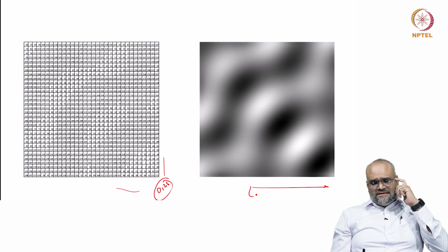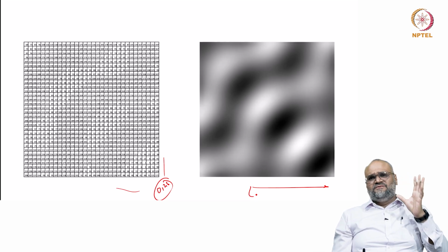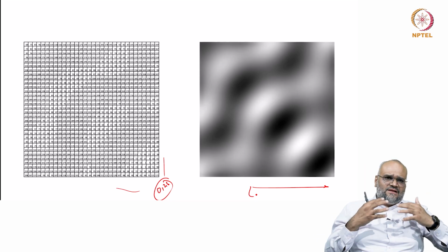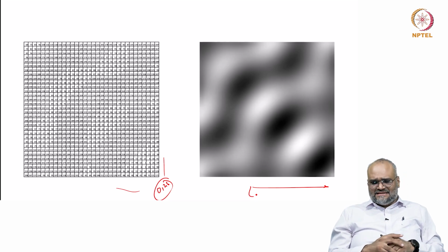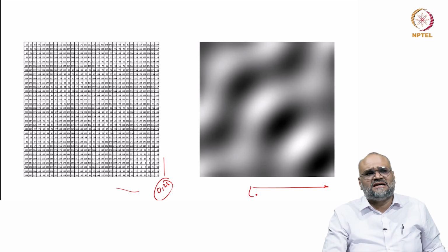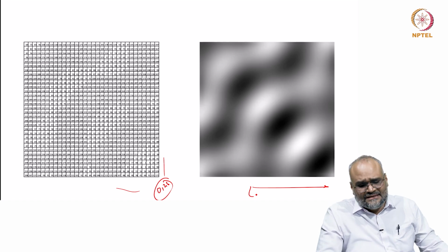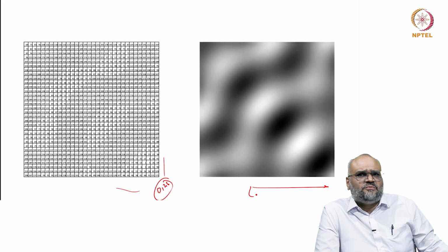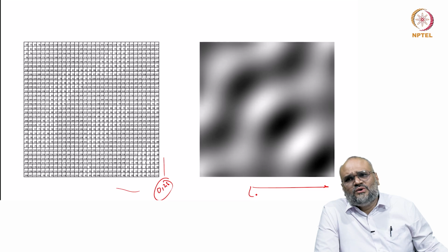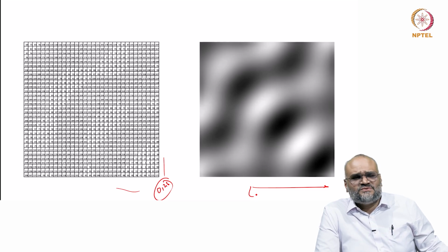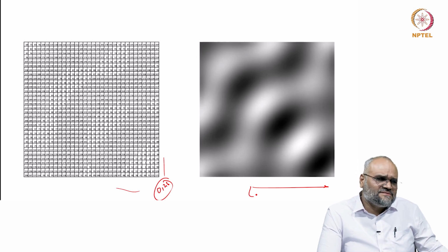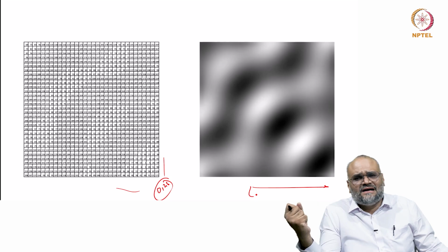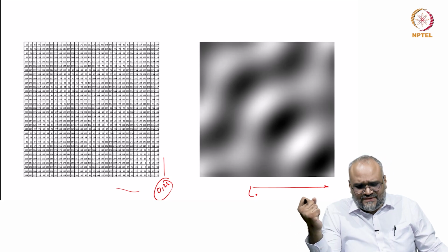So, remember, there is definitely some information regarding the material which you are trying to retrieve and correlate, but the imaging system that is used is displaying only intensity variations which are captured on a fluorescent screen or a CCD camera. And when it is this kind of a process, there can be artifacts which can often be misleading, and before you interpret the intensity variations with some kind of microstructural features, please try to understand why this intensity distribution happens and then correlate it with the knowledge you have on the material. That is when you can do a comprehensive analysis.